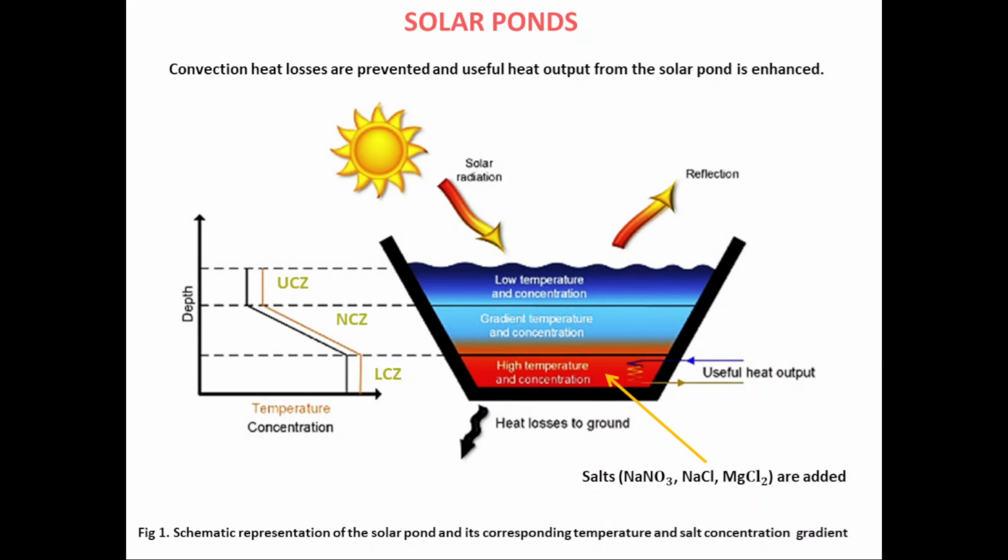It should dissolve in water, and at the same time even the concentration of the salt matters, because each salt has its own solubility limit. If you keep adding salts to the water, and it exceeds the solubility limit of that particular salt in water, then again they won't dissolve and will get precipitated out. So the concentration and whether the salt can dissolve in the water are the two important parameters while selecting salt as a material for your solar pond application.